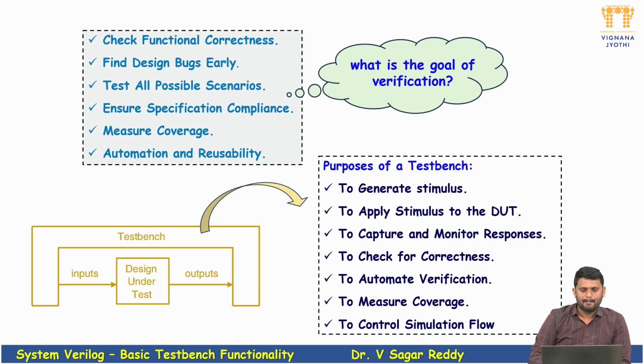To conclude, a test bench is a verification environment built around the DUT that drives the stimulus, monitors outputs, and checks the results against expected values using scoreboards and checkers, and also measures functional coverage. Everything is done automatically, so it removes manual effort, catches functional bugs early, and gives us complete confidence in the design before synthesis.